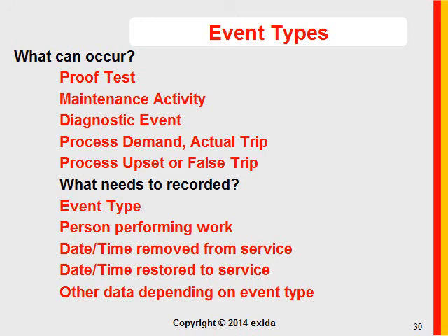But at the same time, we started to realize that one of the things that we as an end user need to do is record and document that we've executed proof tests and mandatory maintenance activities. As part of your event recording in our SIL-Stat software, for example, you can record the fact that you've done these proof tests and that they passed, at what date you did it, who did it, etc.